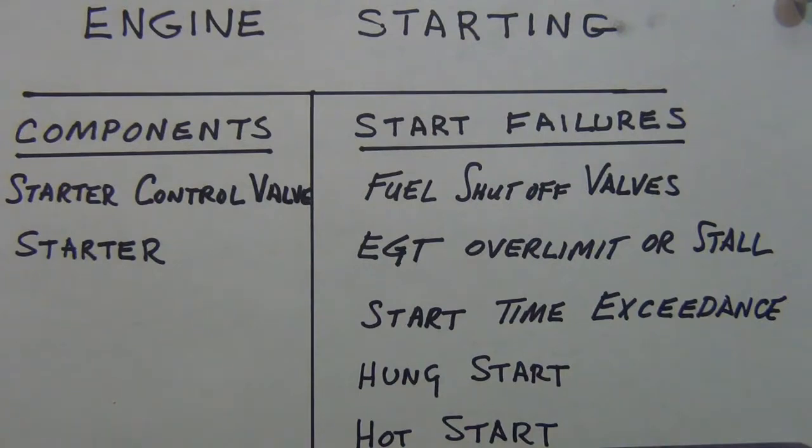The starter time exceeded: you can have this fault where the starter time exceeds what I mentioned earlier. If that happens, then of course the same warnings are going to come on, and the FADEC, if it were in automatic mode, is going to go through that same process of shutting down that start sequence and having the master control switch be off, clearing the ECAM, and then setting the engine mode to the norm position. So kind of a same process there.